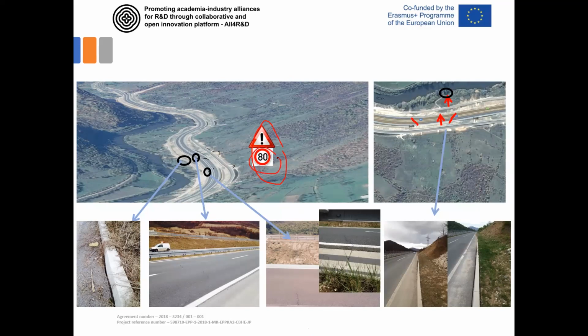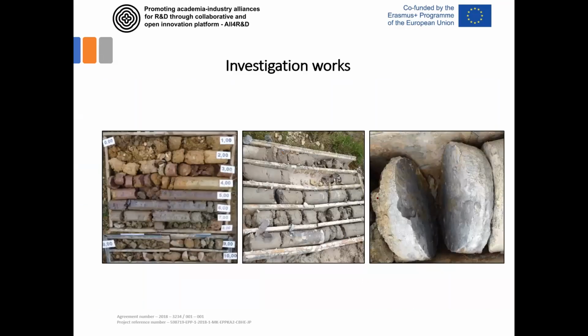So what was done as a practical measure during this investigation is that the allowable speed was reduced to 80 kilometers per hour. The visual observations were continuous, and you can see some cracks here. These cracks and these cracks are on the local road. Comparing the conditions at the winter and at the spring, you can see that some increment in the spacing between the road and this sidewalk is definitely visible even by visual observation, without special measuring techniques.